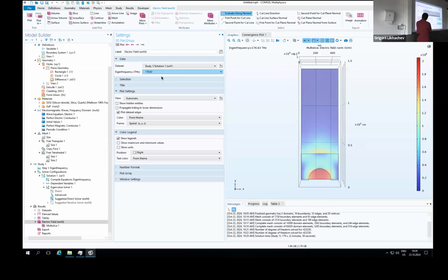What's very nice about these resonators, and this is mainly what you're interested in, is that the dispersion of a ring resonator is linked to its cross section, and usually to have anomalous dispersion you need a narrower waveguide, which means higher losses from scattering on the sidewalls.